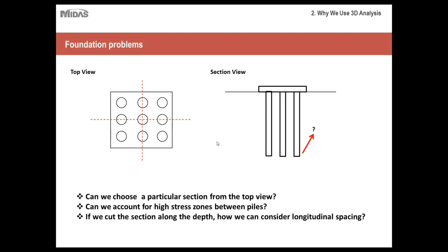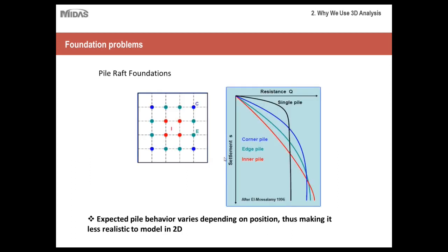So just keep in mind that with group pile foundations, even though the geometry itself may be symmetric, the conditions are not. So that's why foundation problems, specifically group pile foundations, are typically modeled in 3D to get the most accurate results.